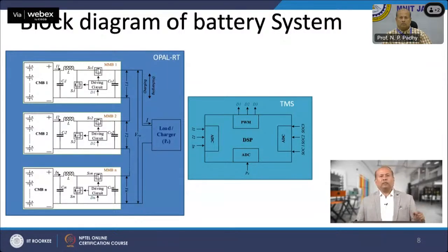To evaluate the proposed control algorithm, an experiment using a built-in MATLAB equivalent circuit model is developed. The simulated model consists of 3 battery modules, and each module is connected to a bidirectional DC-DC boost-buck converter for discharge and charge operation according to the reference current provided to it from the control algorithm.